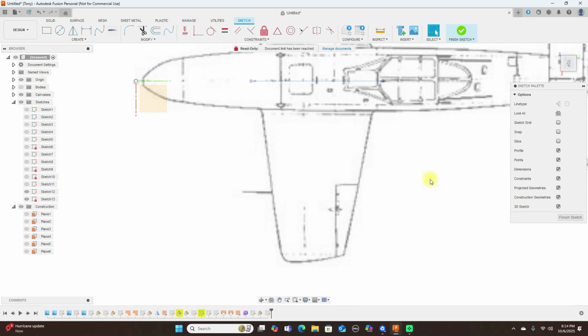And I'm going to use a line. And now you can see it snaps here. And then I'm just going to drag this out here. Now, when you get these pictures off the internet, a lot of times they're not really scale drawings and stuff like that. So always be cognitive of that, and that sometimes, well, most of the times they're not going to line up. So you just have to work around stuff like that. Then select fit point spline, snap that there.